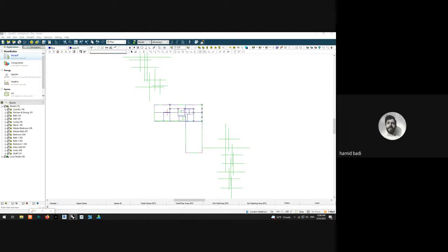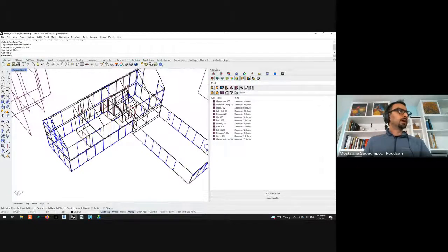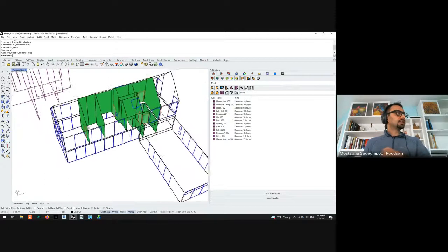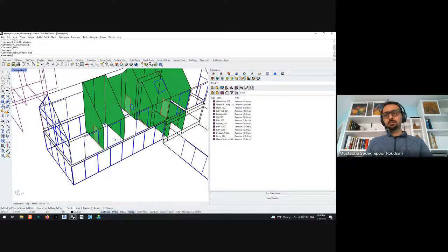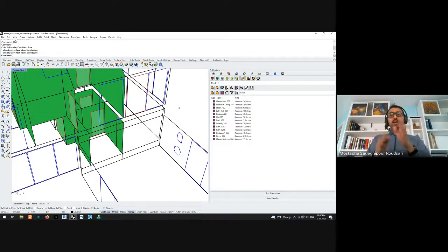Yes, I just opened it in Rhino so I can show people what that really means. You're right, it's not 100% there in Revit, but Revit does a good job. I'm going to only show the surfaces. You'll see it picks up the ones that exactly match. This is the one Conrad was talking about, so it's partially supported. But in a case like this, they are touching, but because they're on different floors, in Revit we don't do intersections. That's why I said we don't go directly from Revit to energy simulation and daylight, because there's stuff like this that still needs to be addressed.